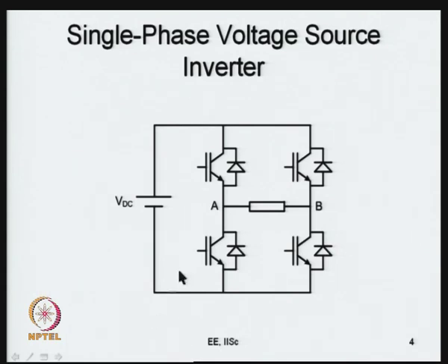So, what do we do? We switch these transistors on and off in a complementary fashion. If the top is on, the bottom is off and vice versa. The same way we can do this, and both these legs can actually be controlled independently.